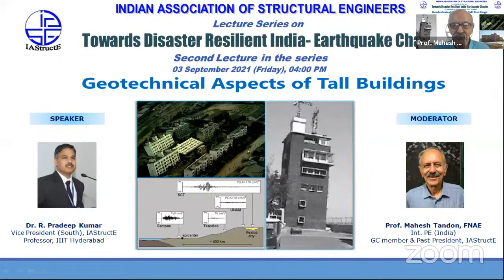These are site-specific hazard assessment for tall buildings, liquefaction potential assessment, and soil structure interaction. Besides this, a structural engineer needs to understand the codal provisions pertaining to the above issues. In the recent edition of IS 1893, a simplified procedure for assessment of liquefaction and recommendations to perform soil structure interaction are included.